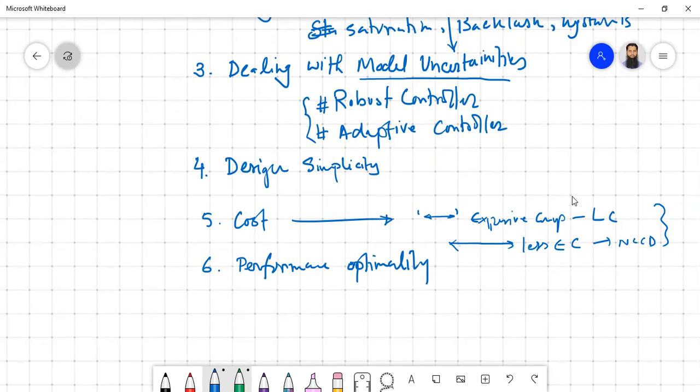And hardly any physical controller has to be implemented nowadays. If you go for digital implementation of these nonlinear controllers, only the computational part is carried out by the microprocessor, which then generates the output or control signal that drives the plant. So it has become a lot easier nowadays, and that is why nonlinear control is now gaining more popularity. The next article is 1.2, nonlinear system behavior.